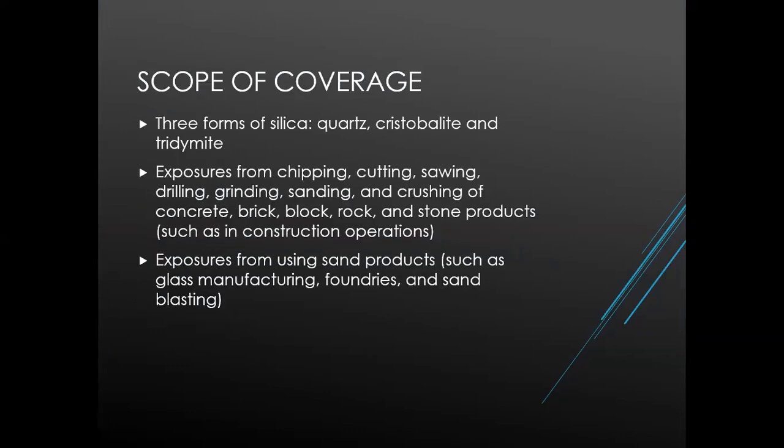This standard applies to all occupational exposures to respirable crystalline silica, such as but not limited to exposures from chipping, cutting, sawing, drilling, grinding, sanding, and crushing of concrete, brick, block, rock, and stone products, as you would find in the construction industry. And exposures from using sand products such as glass manufacturing, foundries, and sandblasting in general industry.